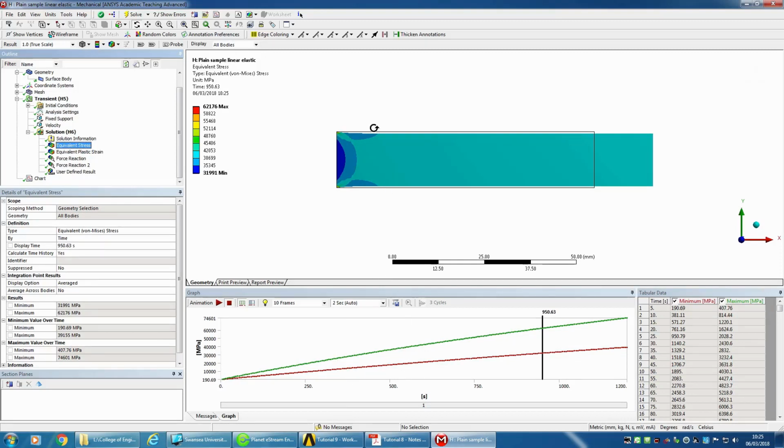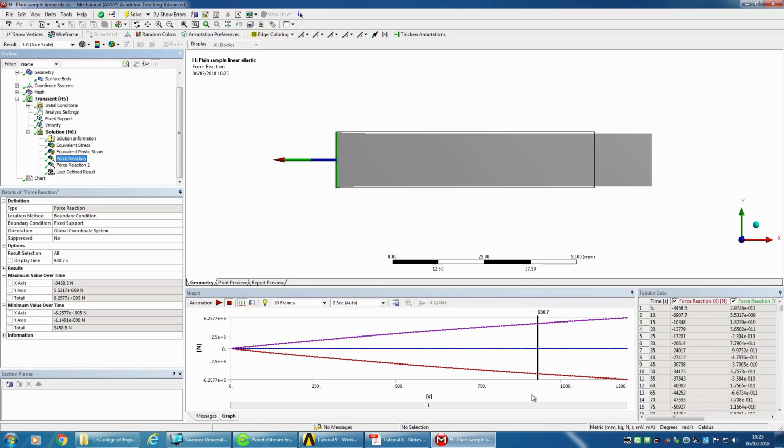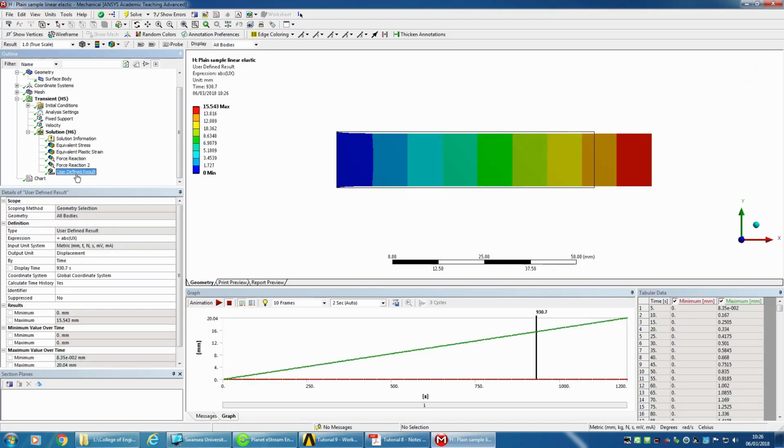So we get these massive stresses, and the deformation, all of it, would be recoverable. If we were to release that, it would just go straight back to its original size. There would be no change in volume, no change in size. It would be exactly the way it was as it started. That shows you the limitations of using a linear model. If you were trying to match your experiment with that, you would be nowhere near in terms of the ultimate stresses or the yield forces that you would see. The deformations would probably not match either what you were getting from the experiment.